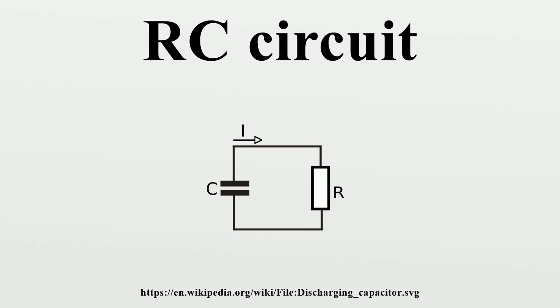RC circuits can be used to filter a signal by blocking certain frequencies and passing others. The two most common RC filters are the high-pass filters and low-pass filters. Band-pass filters and band-stop filters usually require RLC filters, though crude ones can be made with RC filters.